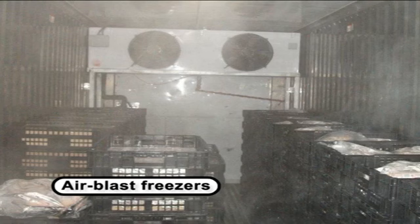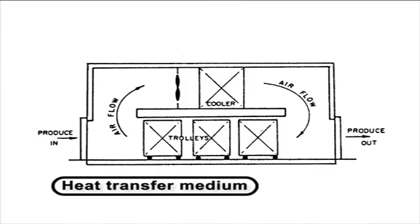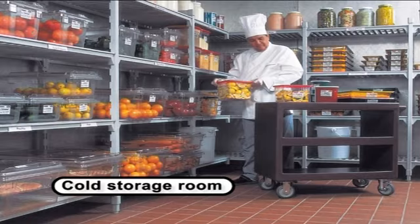In air blast freezers, refrigerated air serves as the heat transfer medium, and the heat transfer is primarily by convection. Perhaps the easiest method of freezing that comes to mind is to place the food items into a well-insulated cold storage room maintained at sub-freezing temperatures. Heat transfer in this case is by natural convection, which is a rather slow process.